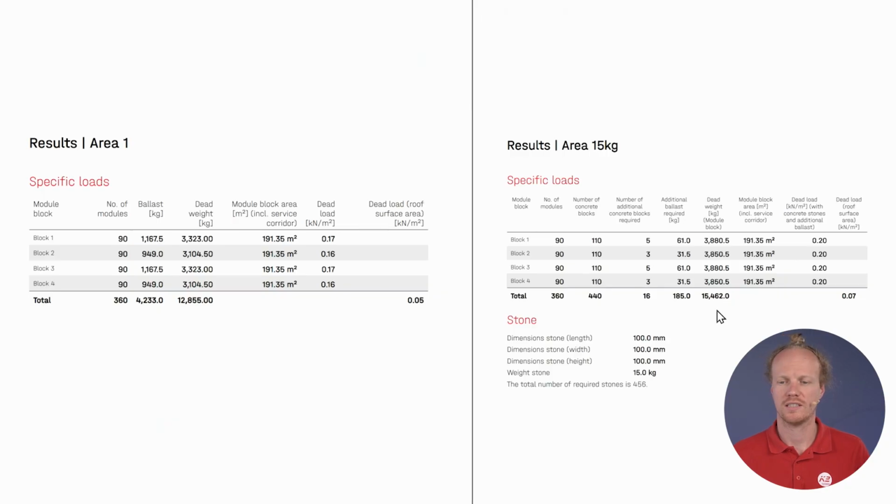You'll also notice in this table there is different information as per the original table with the Mat S. This extra information is useful because it's telling you how many stones are being placed as replacements to the Mat S, in this case 440, and how much extra ballast would still be required on top of that as per the wind analysis for this project.